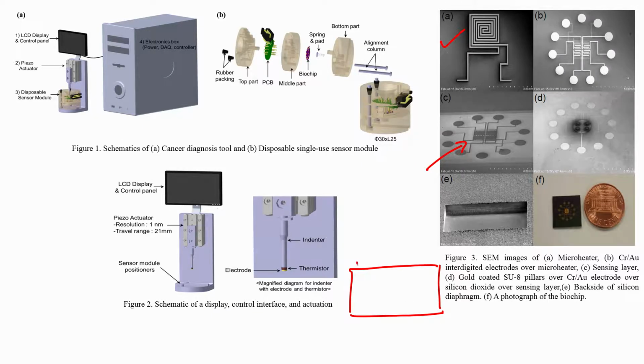Now if you have a piezoresistive material, I will just use a block diagram to make it easier. So there is a heater at the bottom, which I will call H. On that there are, let us say, interdigital electrodes, which I call IDEs, on which you have the sensing material. So I will say piezoresistor, so PZ, alright. Now if I apply force, then the piezoresistor, which are these 4 blocks, should show me the change in resistance, but it will only show the change in resistance when my silicon bends, but silicon is hard. So what can I do?